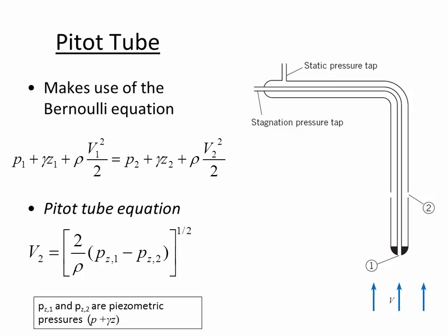It's just a little meter, and it could be measuring pressure, but instead of having the needle point to pressure in an airplane, they will write other numbers on that pressure gauge, and it'll be airspeed. And so they've done the calculations in a wind tunnel, and they've taken this thing onto real planes, and they've calibrated how much of a pressure difference accounts to what velocity. And in fact, that's what this Pitot tube equation tells us, is that the difference in the piezometric pressure at location 1 and location 2 will tell you the velocity at location 2.